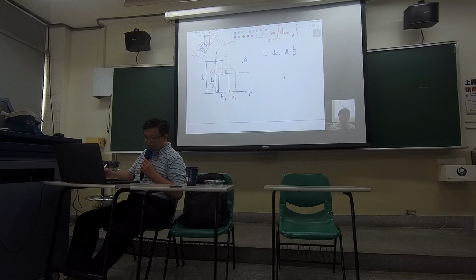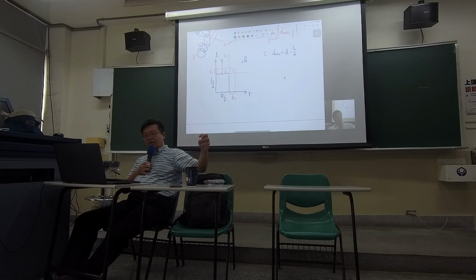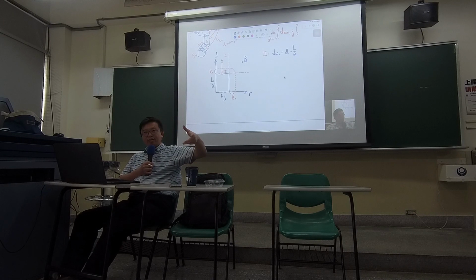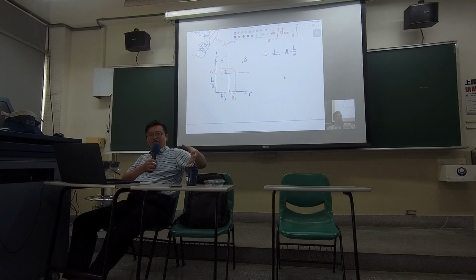So from here you can tell, whenever I know the coordinate of the obstacle, and at a certain configuration for the ith part of my body, I simplify it as a cylinder, and then, based on kinematics, I know where the cylinder is located and oriented.